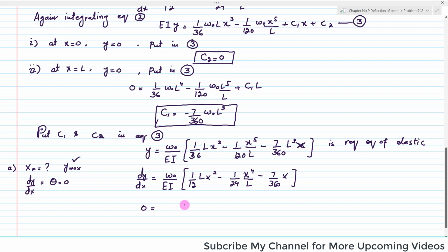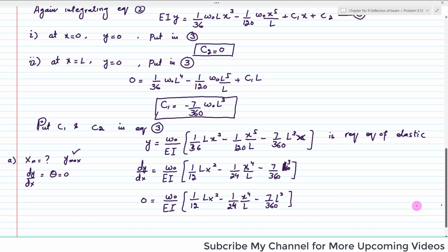So this will be w naught over EI into 1 over 12 Lx square minus 1 over 24 x4 over L minus 7 over 360 L cube, is equal to 0.